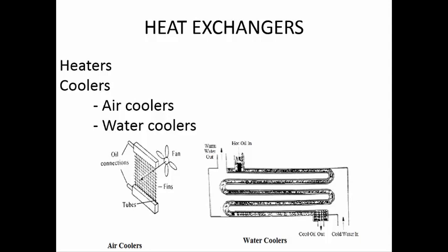Now if you are using a hydraulic system in a very cold environment, you may have the hydraulic reservoir in a sealed environment and the actuator may be exposed to the atmosphere. Then when the fluid reaches the actuator, its temperature has dropped significantly, and it may freeze. That is also possible. So near the actuator you may have an infrared heating element, or a coil, or a pipe with an inbuilt heating element. Near the actuator, you heat the oil so that it has the required temperature and the required amount of viscosity for the actuator to work in an efficient manner.